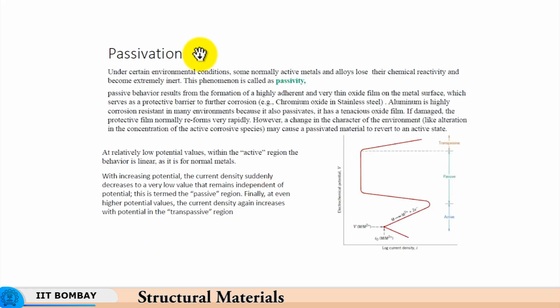Now, we come to passivation. So, let us talk about passivation, and contrary to activation, the material becomes passive in the sense it no longer reacts. So, here what we were talking about is anodic reaction, material prone to reaction, dissolution into the corrosive solution, but when in context of passivation we do not get any kind of loss of metal.